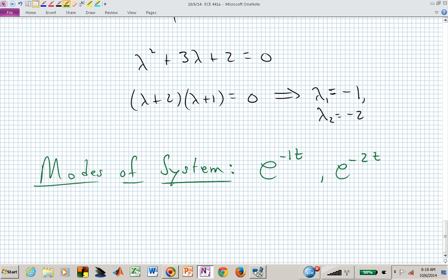And if our system matrix has complex eigenvalues, then what happens? Pardon? Our system has some oscillation. It depends on where those complex poles or eigenvalues are located. If they're right on the imaginary axis, it just sits there and shakes forever, doesn't it? It's an oscillator. It doesn't have any real part.